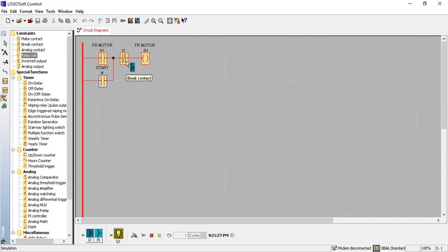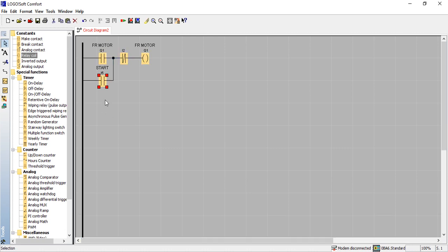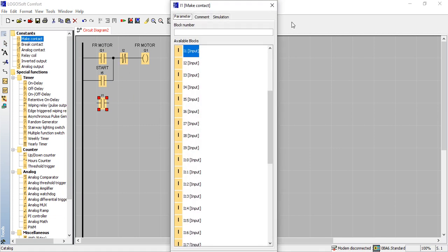So now when I press it, the whole system switches off, and I need to unpress it again so that the system can switch on again. Now you can see that the motor runs until I2, which is okay. So press escape to be able to edit again, and we do the very same procedure.